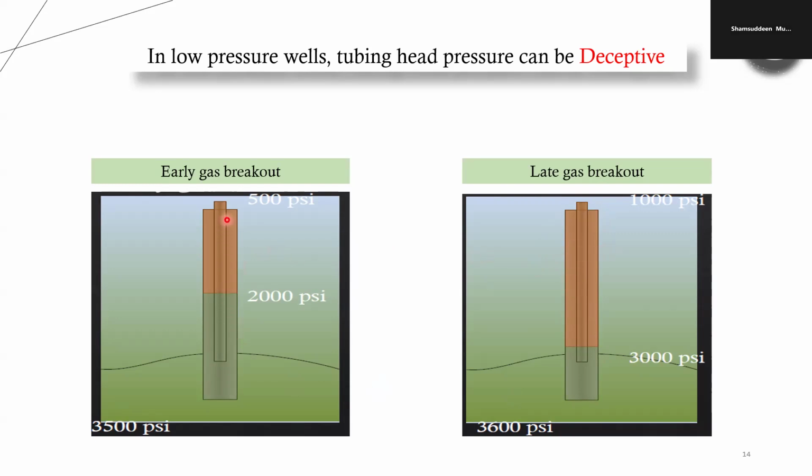But the question is, does the wellhead pressure tell us exactly what we have inside the wellbore? No, because we have many examples where we didn't have relevant historic data, we didn't check accurately or take the right decision. We thought, okay, because we have these pressures, we can open those wells, and then we will have a stabilized flow afterwards, because we think those pressures are enough to make the well flow back again more stably. So we lost some wells on the same day. We lost some wells after 2 to 3 days because those wells did not have enough potential to flow again, because we didn't consider the wellbore condition.